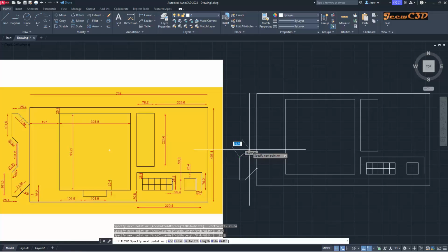I will first press tab key here to access the angles. Then I will have 45. I am not pressing enter. I will press tab again. Now I am on a 45 degree angle. My length is 35.92.